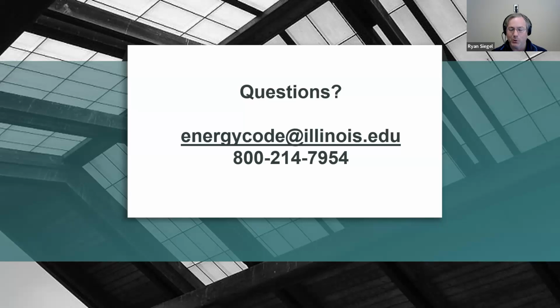But if someone puts in a fireplace and it has a chimney and it has the capability to provide heat to a space, that is a conditioning appliance. I had a question here too, as we were talking about the roof assemblies, and we've talked about sunrooms and porches. Someone brought up that porch replacement projects are a major part of construction work in the city of Chicago. So if the porch is enclosed, does only the porch enclosure have to meet the envelope requirements of the R20 and R5 in the walls? And again, this comes back to, is that enclosing conditioned space or not?